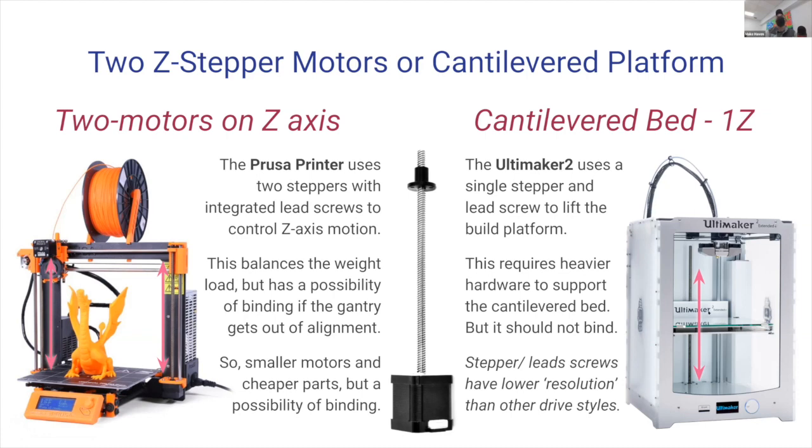Over here, the Ultimaker is another type of printer, and this one is different than the Prusa. The Prusa leaves its bed mostly on the bottom and doesn't move it much. The Ultimaker just takes the print bed and it moves it down, down, down through the entire print. So it's much more like our Markforged printer in that it starts the bed off high and then it lowers it as the print finishes. In this case, you also can see a lead screw here in the back, but it has these beefy rails so that the lead screw is just raising and lowering, and it's not really fighting against the tilt of the bed. The bed would want to sort of flop forward if it was let to go loose. And so these are two different stepper motors that you might use for a Z stepper.